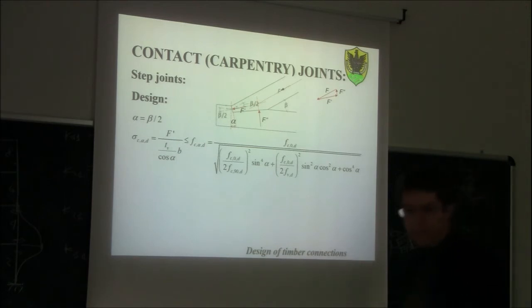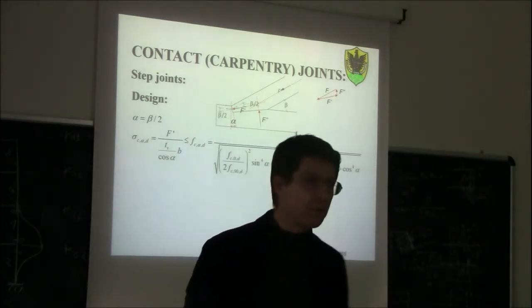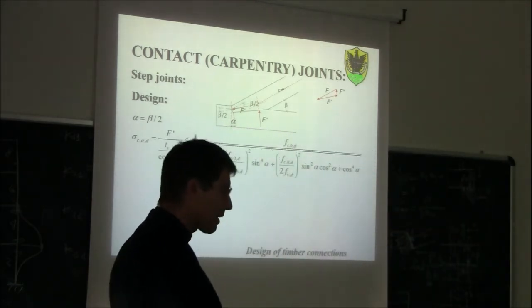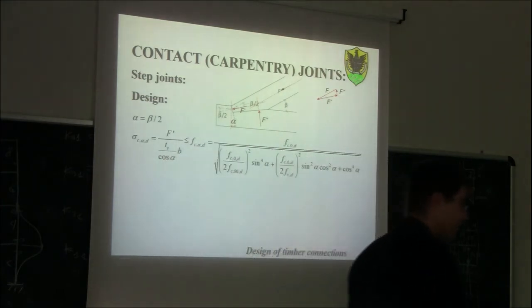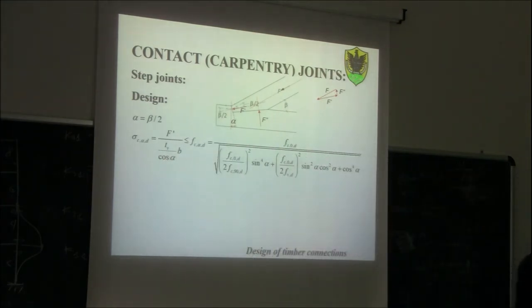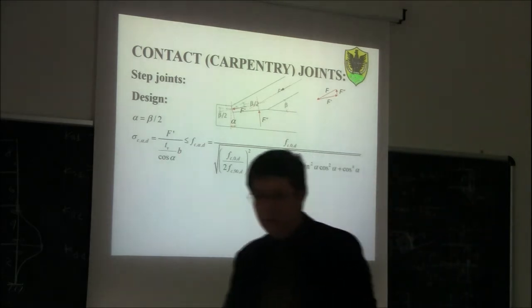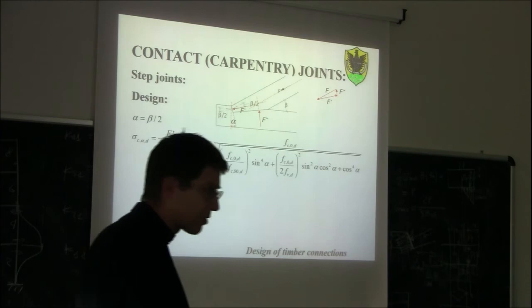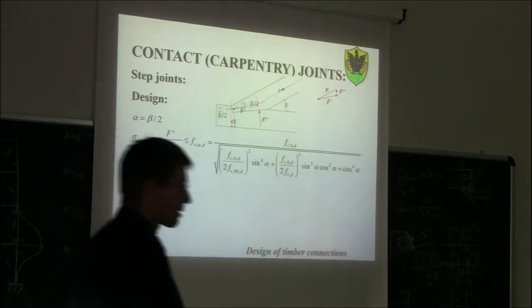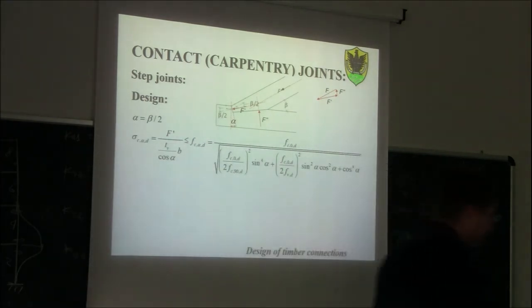Since very often we have to use these formulas not for new construction, but to check the stability of existing construction, the problem was that by using this Hankinson formula several times, we would have to change existing king truss. For example, in beautiful churches, this existing king's truss would not satisfy this Hankinson equation, while instead they did some experimentation and found out that they were okay.